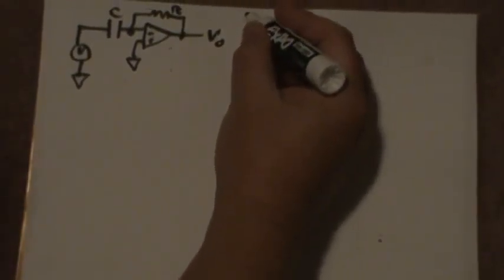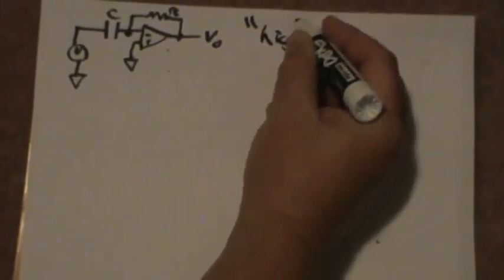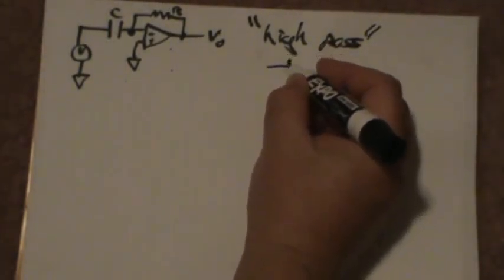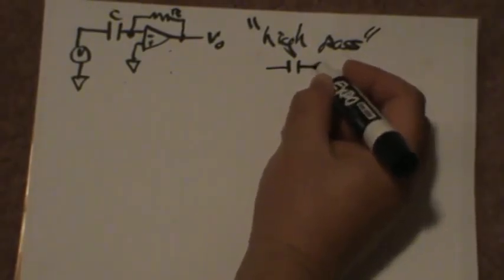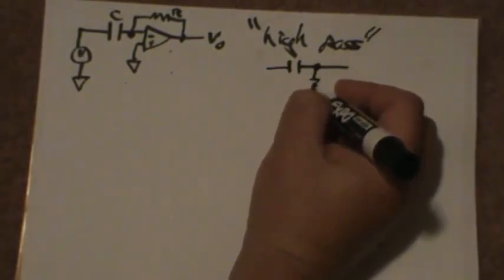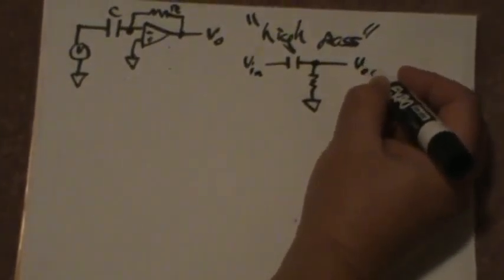Now this has a second function that becomes apparent when we take a look at the equation. So we should look at this, and our first thought should say, this is high pass. I say it's first order because it's just a simple first order system. This is akin to what you would get with a simple first order high pass filter, which just looks like that, where you have your V in and your V out.